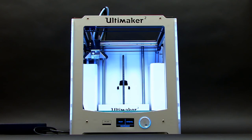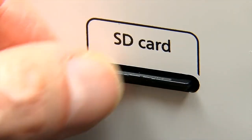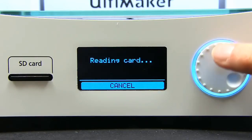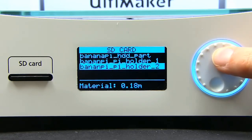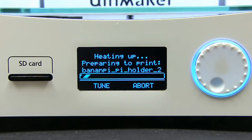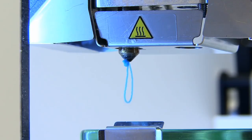Right, it's now time to visit our patiently waiting Ultimaker 2, into which we can insert the SD card containing our G-code files. I'll start with the smallest print, so we'll select Banana Pi Holder 2. The printer then needs to heat its build plate and its printhead, after which the build plate will rise up, filament will emerge and printout will start.